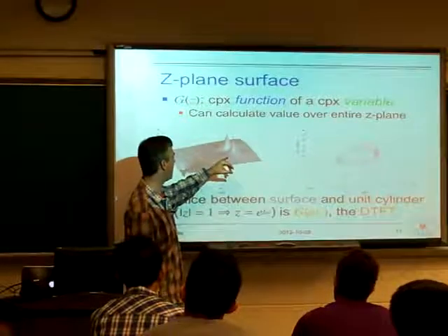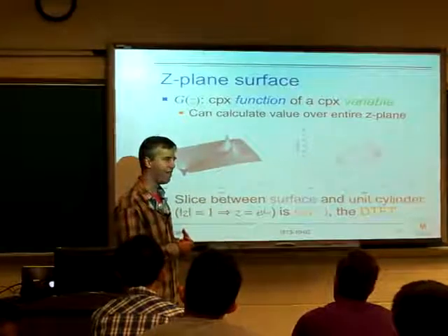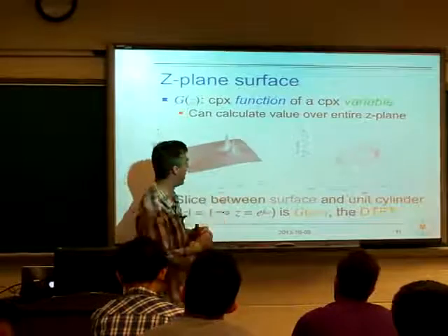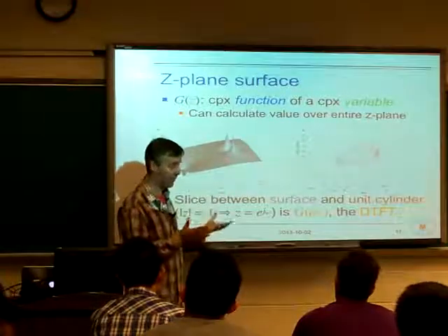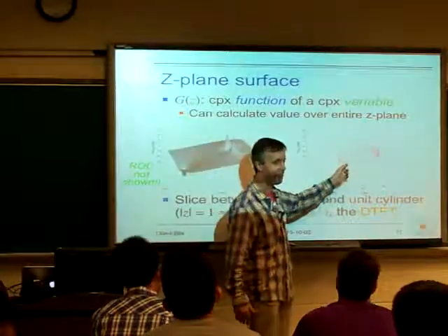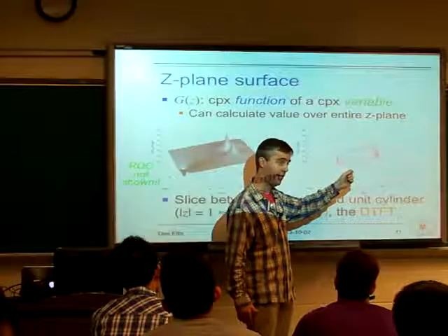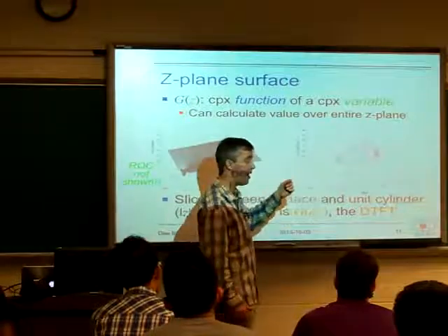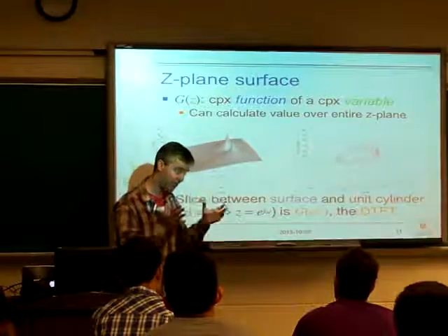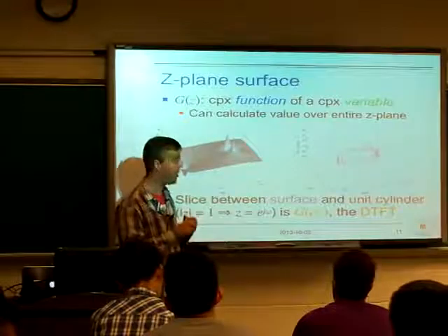This was the Z transform of some sequence, and it had a region of convergence, which meant that it was true for some set of values of z, and there were other values where it didn't work. Now, I started talking about the Fourier transform as the values of x of z for z of unit radius. The x of z I'm talking about there is not the closed form expression, it's the actual Z transform, meaning I have to think about the region of convergence.